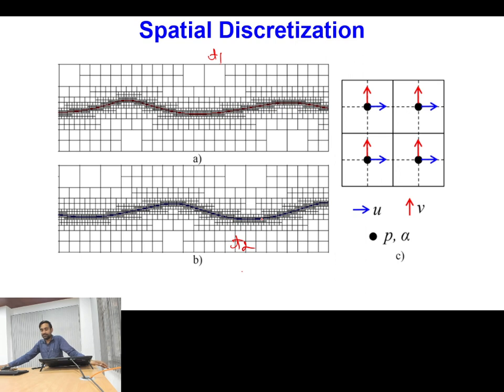Though adaptive mesh refinement is also implemented in certain solvers for unstructured meshes, majority of the time it is better to use this with structured meshes, because in unstructured meshes, if we go with a large level of refinement, then if you use the finite element method, there is no problem, because in the finite element method, the node points are used at the center of the control volume as well as on the boundaries. So the number of node points is more than one in a single element. But in the finite volume method, where the node point is only at the center of the control volume, it may give some errors if your cells are too much skewed and not aligned with the interface.